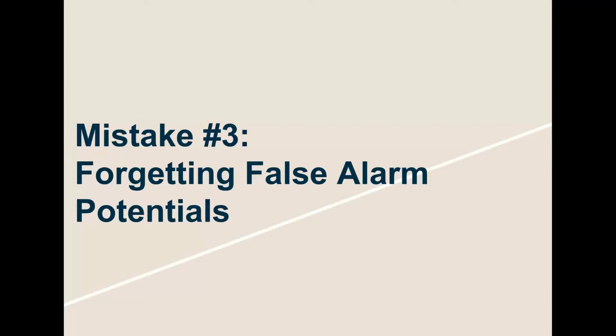So, from a Draeger design standpoint, when you guys are doing designs for flame detectors or for gas leak detectors or what have you, what are some of the major key things that you really try to get customers to remember that they need to do in the design phase? Yeah, probably one of the most important things is to know the process, right? To know what the different gases or vapors are that might occur during the production process or when the process is running.